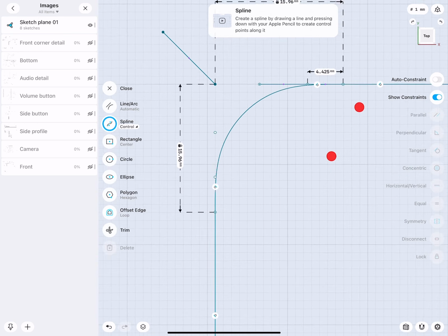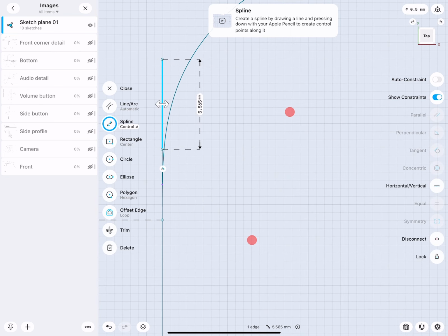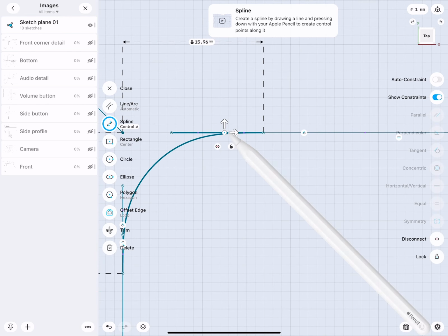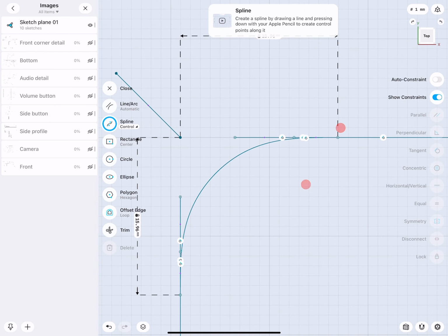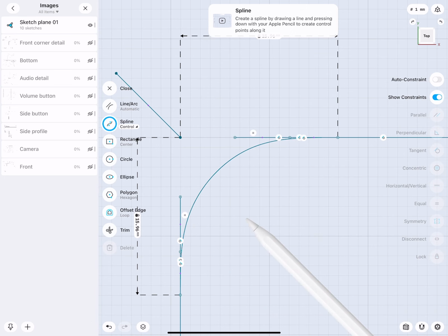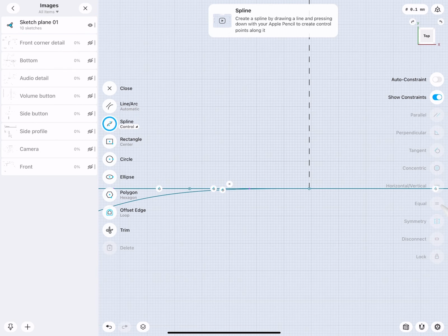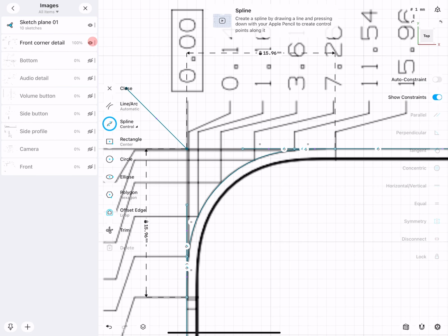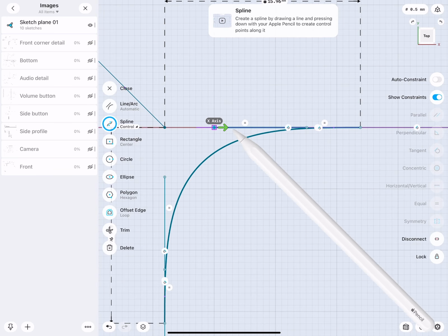I draw a line and I draw a line. The line to this should be tangent, and this to this line should be tangent. This actually prevents this point going up and down. And these two lines I would like to be equal, and these two lines I would like to be equal. It's a very simple set up to actually create geometry-driven constraints. So when I select this point, you notice that the other point actually moves with it. How awesome is this?